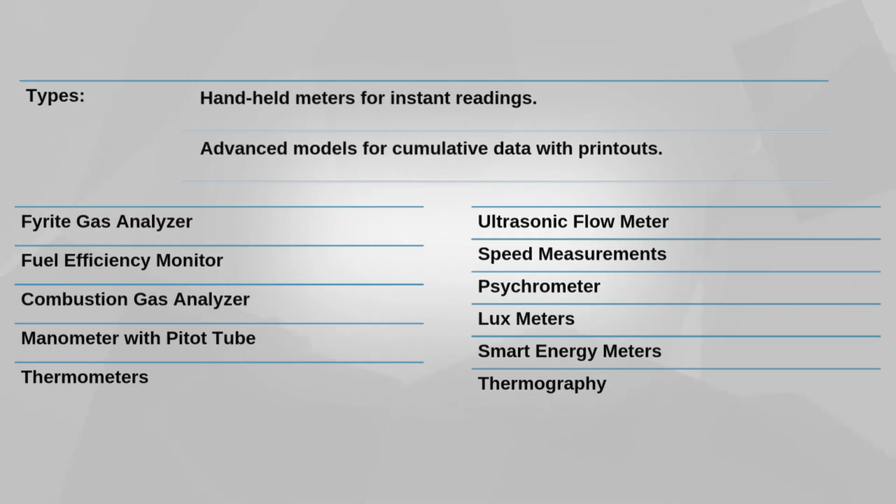Next is thermography. Infrared thermal monitoring and imaging, or thermography, measures thermal energy radiation from surfaces. This non-contact method helps assess equipment health and supports predictive maintenance by identifying hot or cold spots. The thermal camera converts infrared radiation into electronic video signals, which are analyzed to interpret temperature variations.